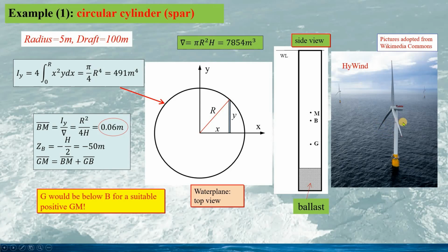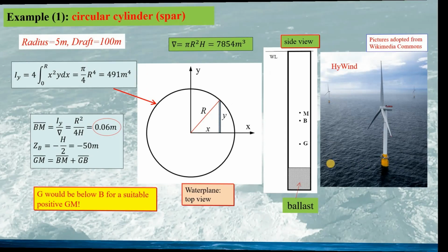This floating wind turbine might not be affected very much by the wave, since this relatively small water plane area means transparency in hydrodynamics. But this floating structure must be deployed in deep waters. Generally, the water depth must be considered more than double of the draft.